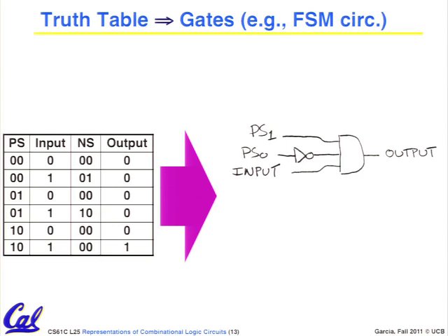So by inverting the bits that are not the case, I have this really pretty pattern. Give me a bit pattern: 101. Well, then I say 1. Whenever you said 0, I put an inverter there, and I put all that in an AND gate, and now I get something that only goes high when the exact bit pattern is present on those input bits. 1, 0, 1: the 0 becomes a 1, so 1, 1, 1, and therefore it is only going to trigger high when all of those are true. Therefore, only that signature is going to be the case.